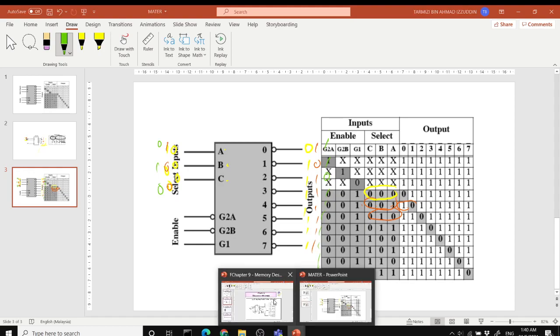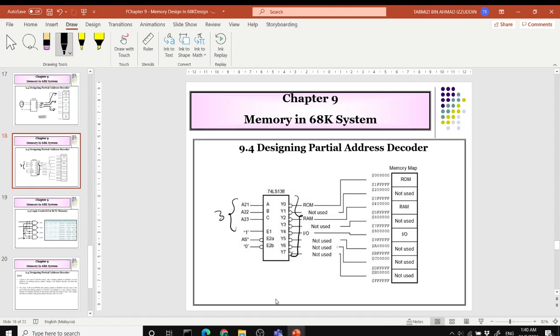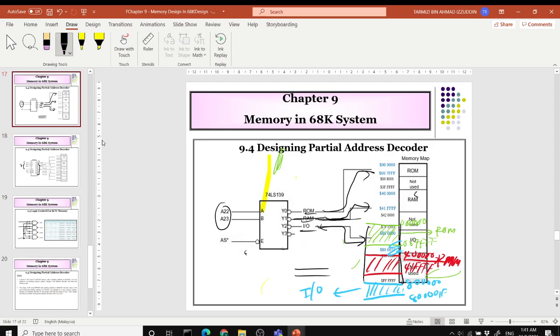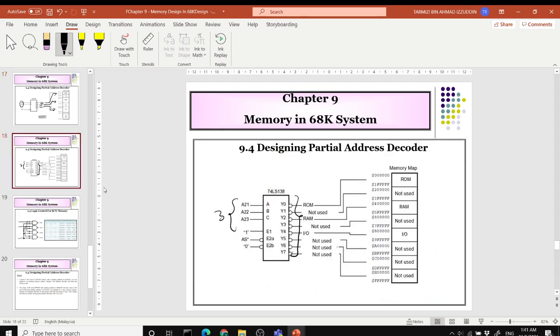You can use 74LS138. It's up to your preference, but in general, if you require only 3 peripherals, then it is best practice to use 74LS139, because this contains the exact number of peripherals that you can connect to, whereas if you use 74LS138, you have a lot of unused pins, so it'll be a waste of input and output.